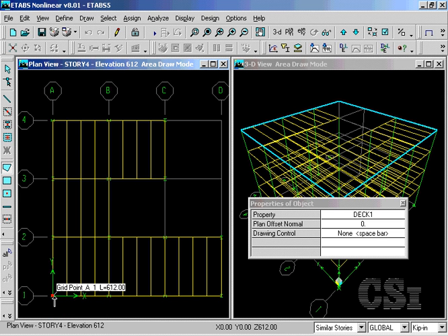Click once at column A1 and every other corner as you move clockwise around the model to draw the outline of the building. Press the Enter key after returning to A1. Note that the two-headed arrow indicates the direction of the deck span.